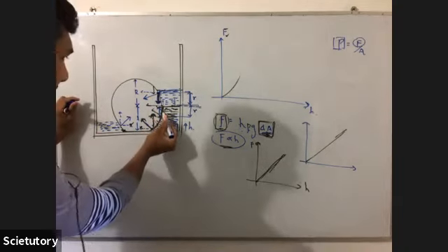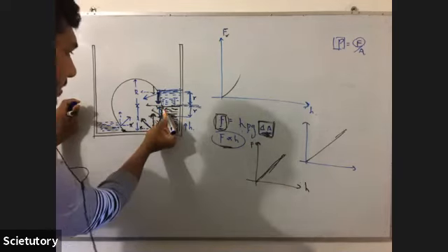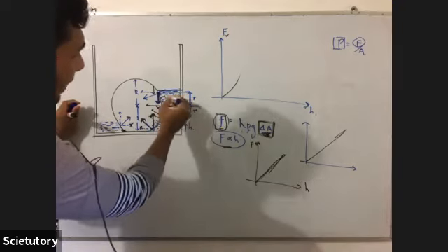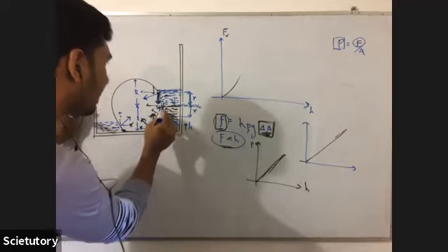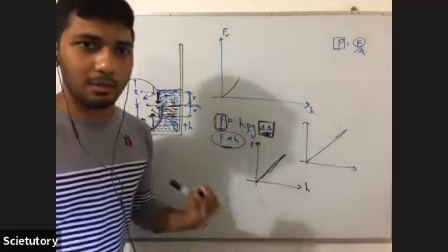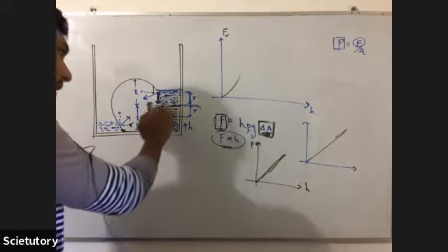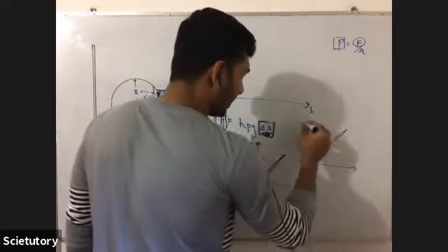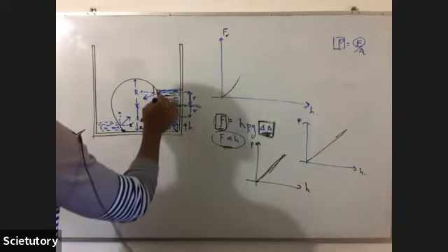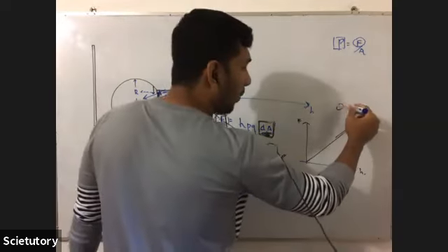The whole area is creating upward force. This is all now wet. So when you increase the height after this point, the force on this surface is going to increase. The upward force will be increasing. If it is the only part that we consider, the graph will be like this. But there are newly generated forces, and they will have an opposing effect.